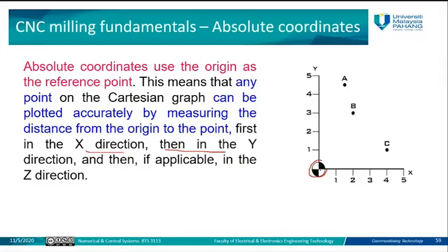So for example, here I'm in the reference point. How will the spindle or the head of the machine, or the coordinates of this workpiece, be changed? I start from 0, 0. Should I go up or right first? What is the first movement of this part from the 0 point? In the CNC, meaning if it consists of 2 or 3 axes, first you need to go through the x-axis. That means this head will move on the x-axis until it reaches the point of 4.